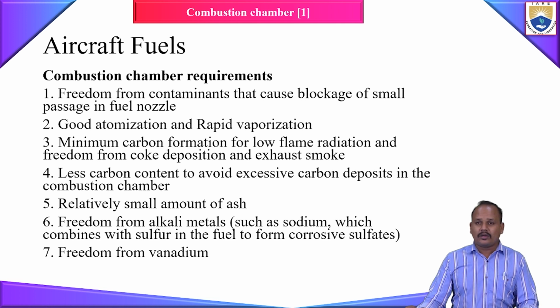What is going to happen if we have sodium? When it combines with sulfur, it is going to form corrosive sulfates, which is once again going to affect your environment. And freedom from vanadium, which is also related to the environmental effect. So these are all the requirements which the fuel needs to satisfy if I'm going to use it for aviation purposes.